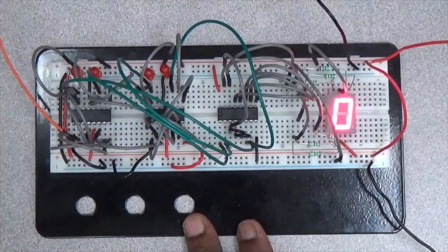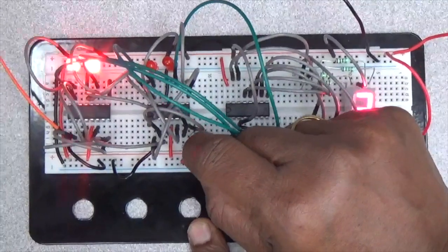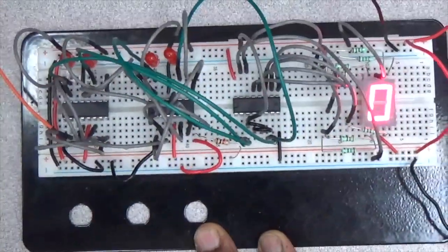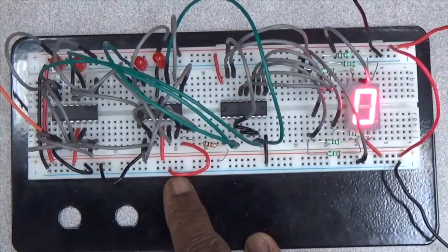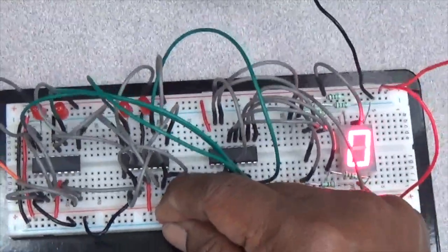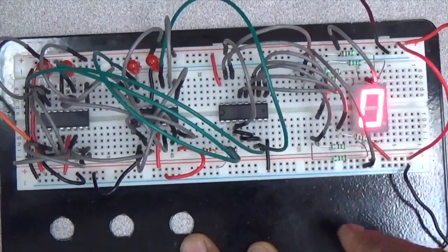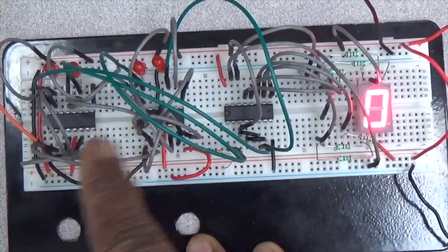This is the push button I showed as a wire. So this push button has to be grounded initially to start the count sequence, and when you put in ground, the count is 0. Okay, when I take out this, the count sequence would start from 1. On the display you can see 1 to 9. You can also verify through this.